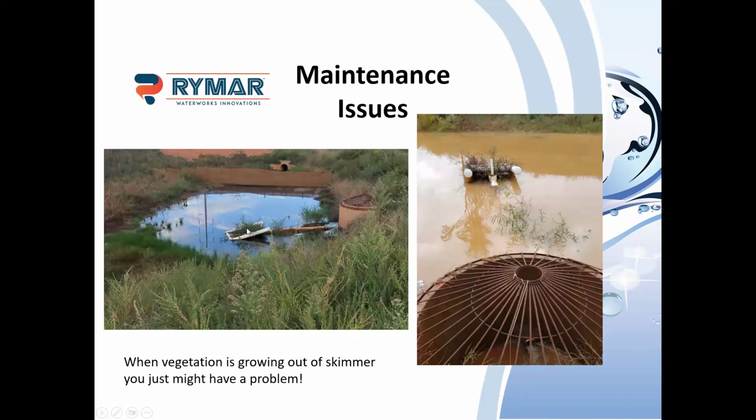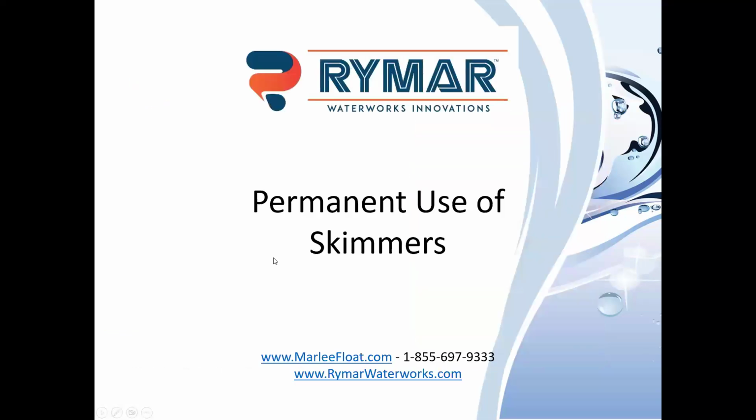This one too has some vegetation growing out of the skimmer. So skimmers are not maintenance free. They do require some maintenance, some more than others, but in this case, the skimmer had a big root ball inside of it. So the pond was not draining at all like it was supposed to.